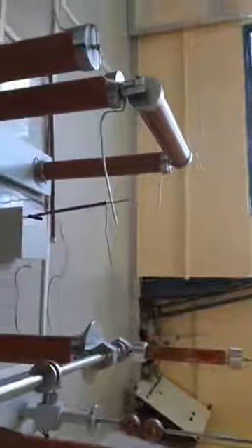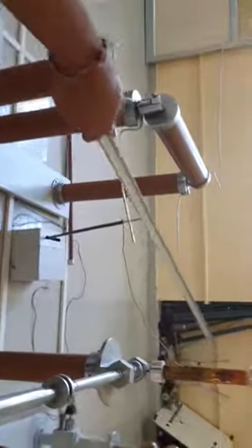Now you can observe here, once the breakdown occurs, or once conduction takes place between the two electrodes, the leakage current or discharging current goes into the ground potential. This is the ground connection box that you can observe here. Through this box, once the breakdown occurs, the discharging current goes into the ground potential, so that the entire device is protected against the breakdown.